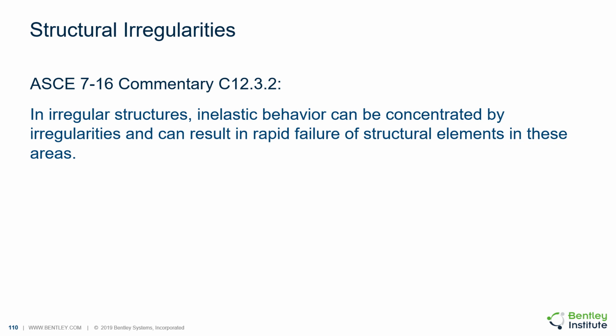In irregular structures, inelastic behavior can be concentrated by irregularities and can result in rapid failure of structural elements in these areas. Remember that during a severe earthquake, the frames are expected to deform inelastically. This inelastic demand is expected to be shared by all of the frames.